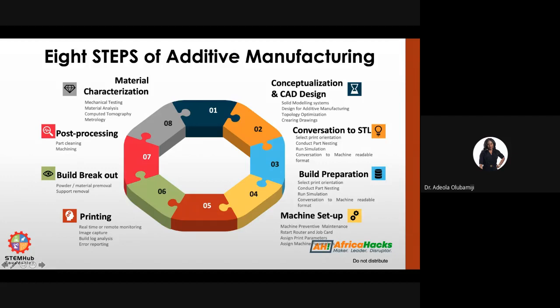In some cases, like everything Johnson made today, in machining you can't machine everything together. But in 3D printing, I can print those 4 components as one piece. All I need to do is merge the 4 parts into one part, remove some areas, fillet some areas, and make that part printable using the particular 3D printing technology that I have chosen, and then I'll move on.